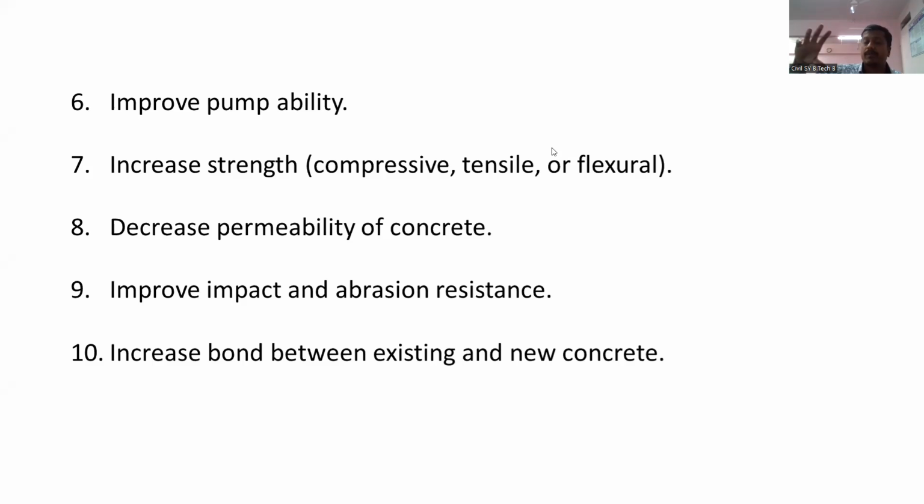Okay, on whatever concrete body you are having. As we know, our concrete is strong in compression and weak in tension. So if you want to determine the tensile force present in a given concrete, we are going to use the split tensile strength. You are going to cast the cylinder and then apply the load. The cylinder will split into two different parts. Okay, so that is the tensile strength as far as our concrete is considered.